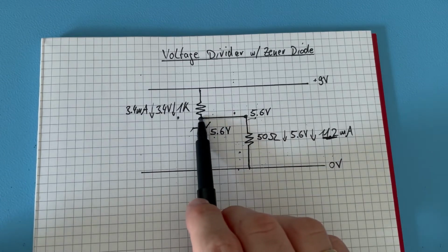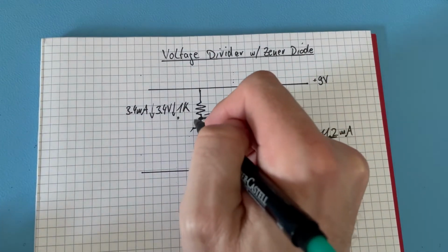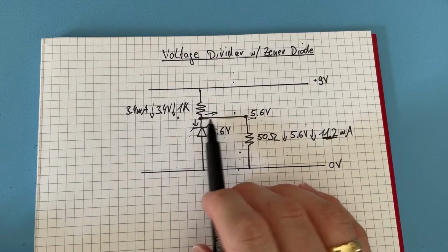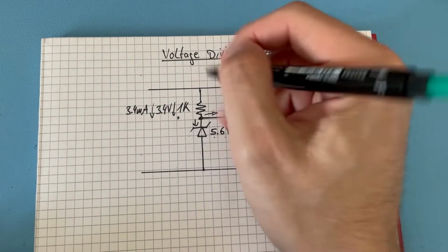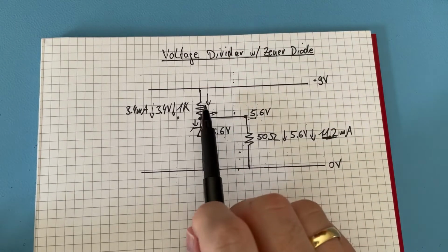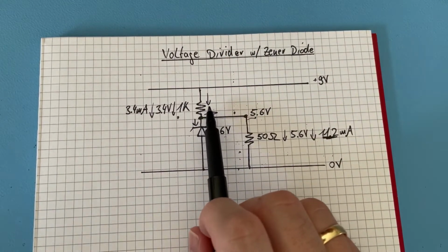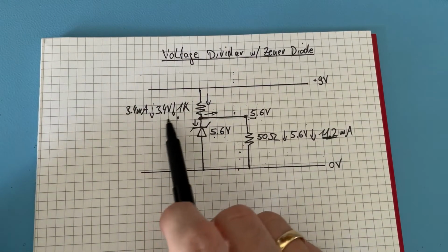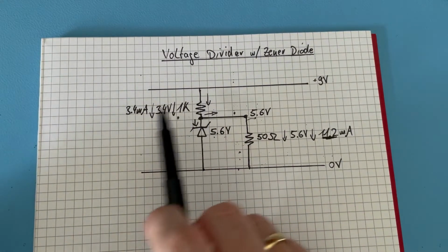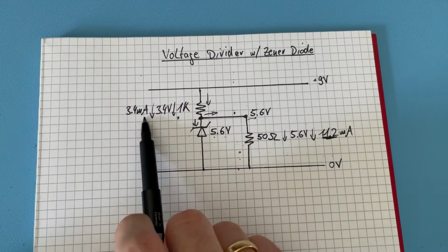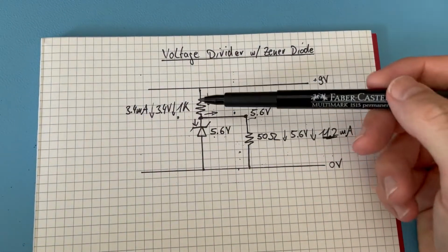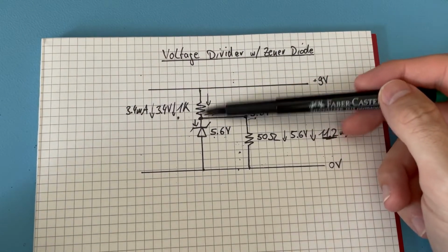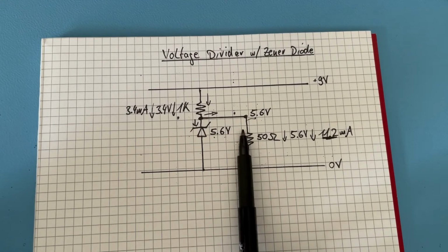So we have leaving in this and this direction at least 112 milliamperes, but these must also come in through up here, and that is not quite in sync, because we said having 5.6 volt here, there must be 3.4 milliampere through this resistor because of the 3.4 volt difference. And I really wonder what would happen here.